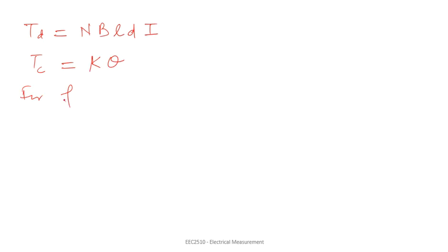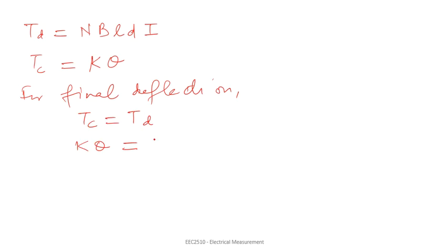For final deflection, the controlling force will be equal to the deflecting force. So k theta is equal to the deflecting force, that is equal to G I, where G can be taken as a constant.